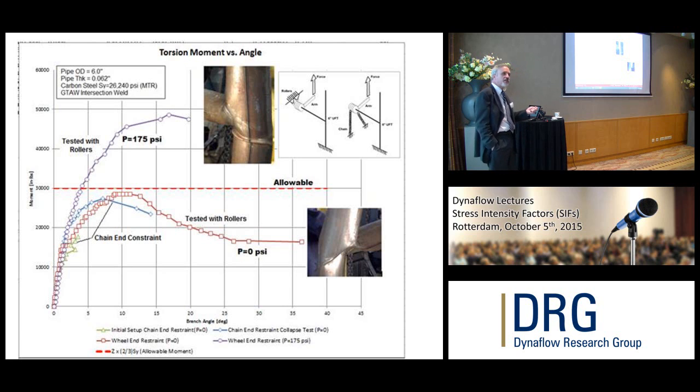Okay, the last thing, but not least: the new version of Caesar now includes a sustained load case for every operating case. That was B31.3 guidance in 2014. So you'll have a whole lot more sustained load cases than you ever had before running Caesar with B31.3. So you will have more sustained load failures.